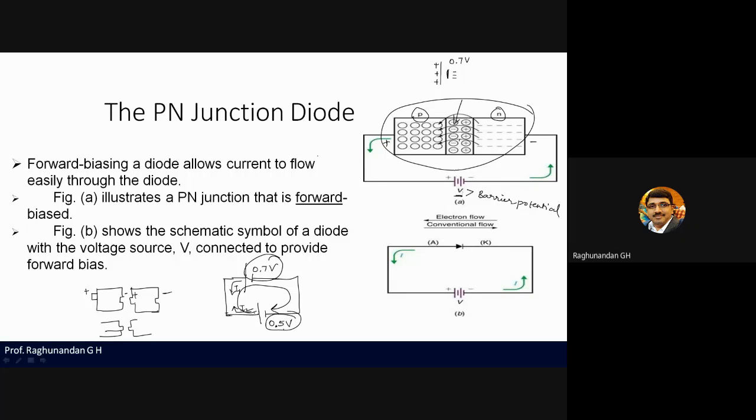So now if you want the current to flow through the circuit, then you need to make the input voltage greater than 0.7. So same thing, I'll make it as 0.8. Now which current will flow? I2, sir. I2 will flow because I2 dominates over I1, so that will flow.